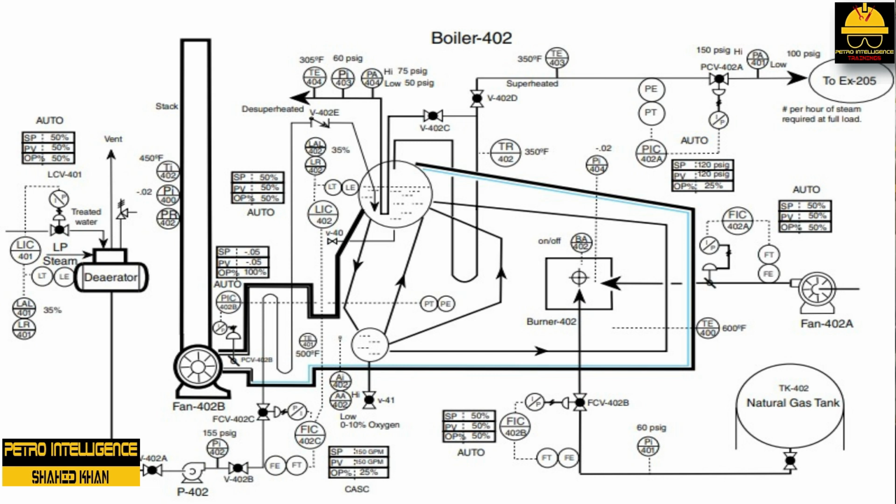To start the system, follow these steps. 1. Notify your supervisor and all concerned about startup. Downstream process technicians, instruments and electrical, engineering, maintenance, etc. 2. Ensure all safety hazards are secured. Trash, locks, old permits, etc. 3. Check equipment and instrumentation. Stroke control valves 0 to 100%, check lineups, etc.